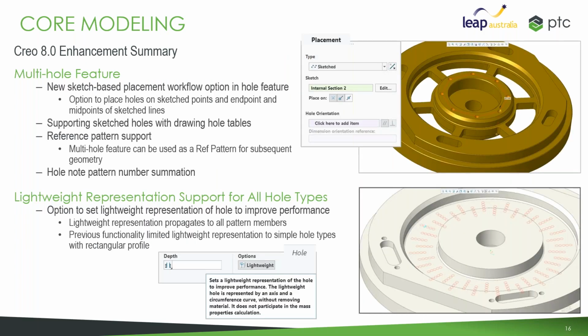There's a new multi-hole feature option. Now, I know a lot of you, we tell you in the training you should create hole features rather than an extruded sketch, and you still go in and create a sketch with a whole bunch of circles in it. So now we can actually create a hole feature with all of the advantages of holes, the ability to change the sizing and switch it to a standard hole and tapping and all your other options, but a new multi-hole feature based off a sketch. So I'll have a look at that in the demo.